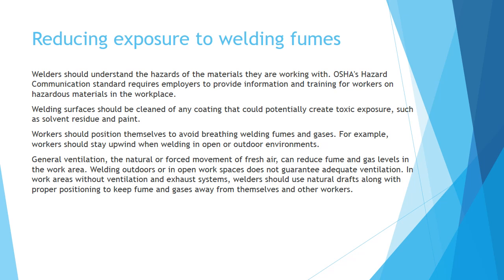General ventilation, the natural or forced movement of fresh air, can reduce fume and gas levels in the work area. Welding outdoors or in open working spaces does not guarantee adequate ventilation. In work areas without ventilation and exhaust systems, welders should use natural drafts along with proper positioning to keep fume and gases away from themselves and other workers.